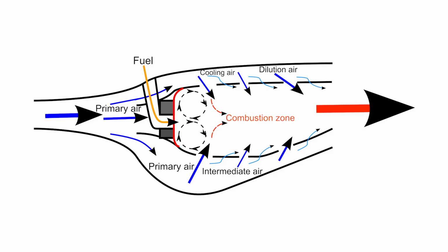Intermediate air is the air injected into the combustion zone through the second set of liner holes. This air completes the reaction processes, diluting the high concentrations of carbon monoxide or CO and hydrogen or H2, and also helps cooling down the gases from combustion. Dilution air is air injected through holes in the liner at the end of the combustion chamber to cool the flue gas before it reaches the turbines. The air is carefully used to produce the uniform temperature profile desired in the combustor.